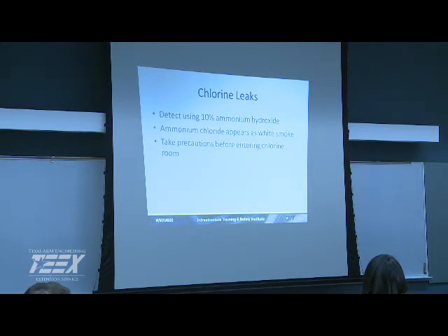We had an issue when they went through the construction of our facility. They had vents for our vacuum regulators. Well, they vented them right out to the front of the building. That's where our meter was. So you go up there to see if you have a leak, and it's venting right there in your face. So needless to say, we relined them, replumbed them out to the back, and put them in a vault with a sensor. So if you did have a leak, it's contained in a small underground vault, and it lets us know through SCADA.